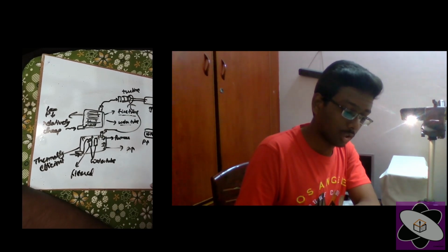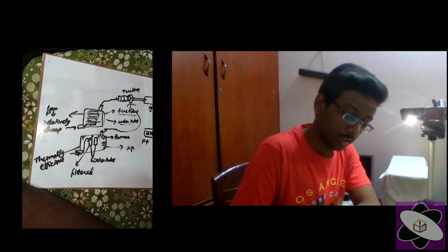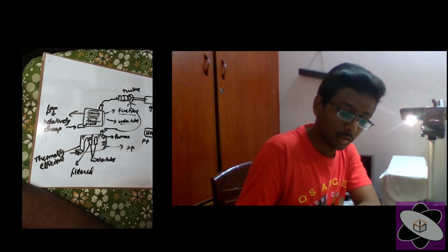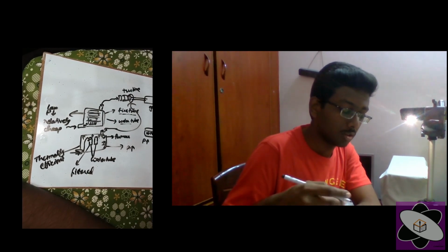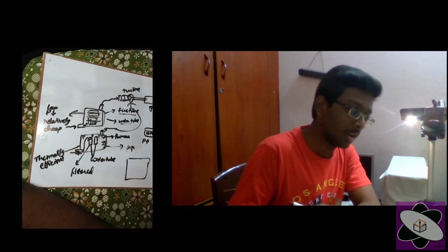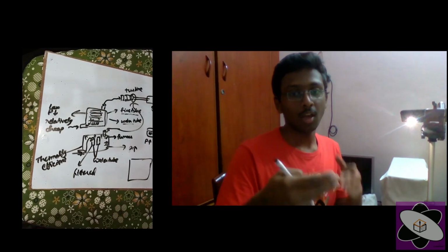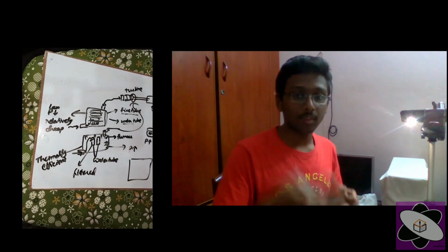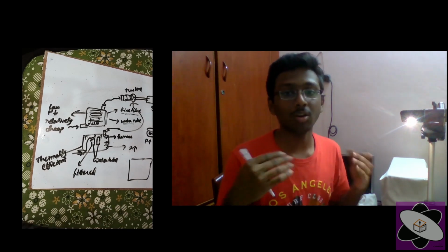And one more thing, the things which can happen are boiler corrosion, rusting, sludge formation, flux formation, all those can happen. What are the side effects of this? If sludge formation takes place inside the boilers, the heat will be spread unevenly. In front of the sludge there will be one temperature, and at the back some other temperature, or on the sludge we have one temperature and around it another temperature. Because of that, heat is not distributed evenly.